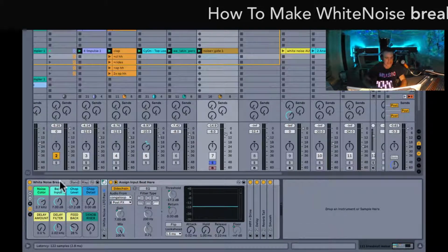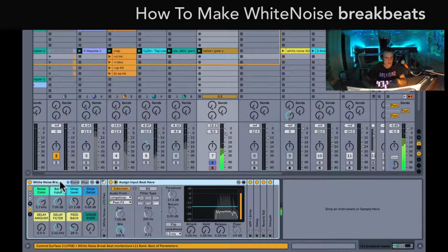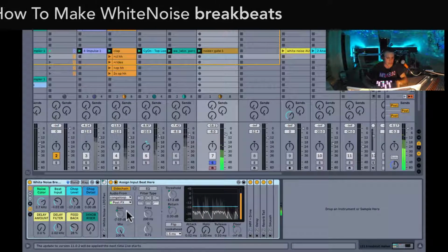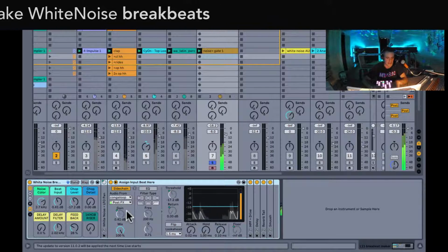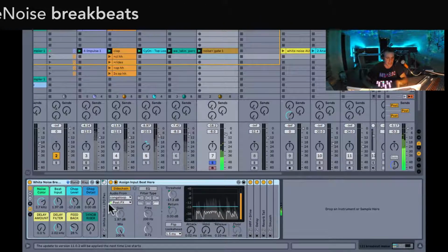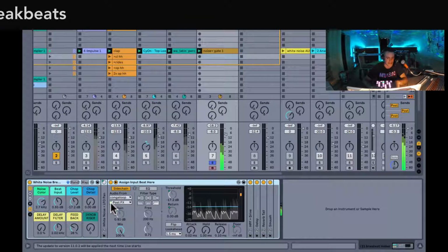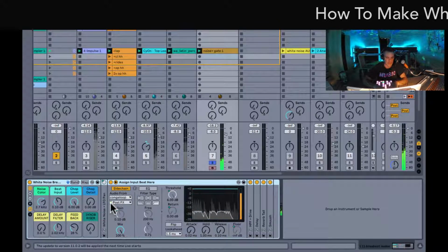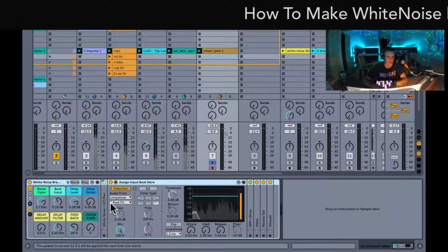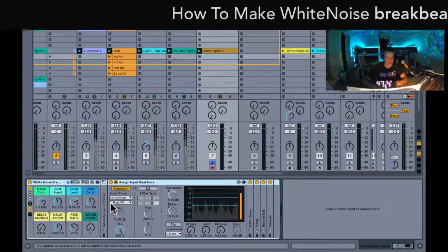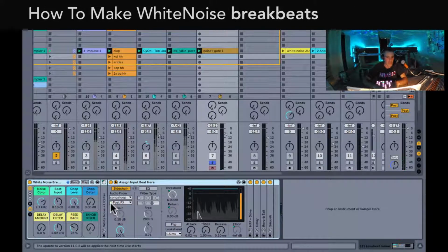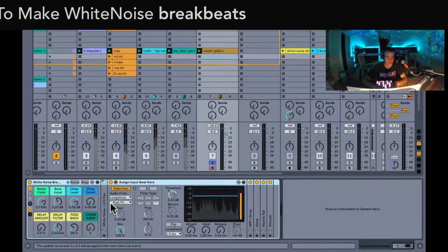The idea is that to get the gate working, you need to have the input sound at the right level. So I gave you a knob for input that's matched to the input gain, and you want to adjust to the level of the sound coming in. You can look in that tiny little meter to make sure you got green bars bouncing. Then there's a knob for chop level and chop detail, and that's for gate threshold and return. The threshold is where the gate opens, and the return is how long the gate stays open before it closes. So right now we got nothing because the threshold's too high, the input signal's not crossing it.